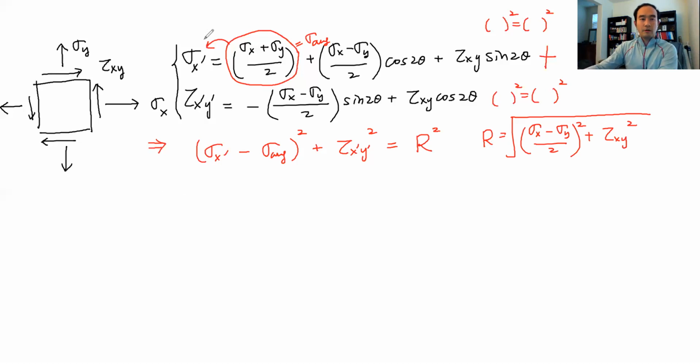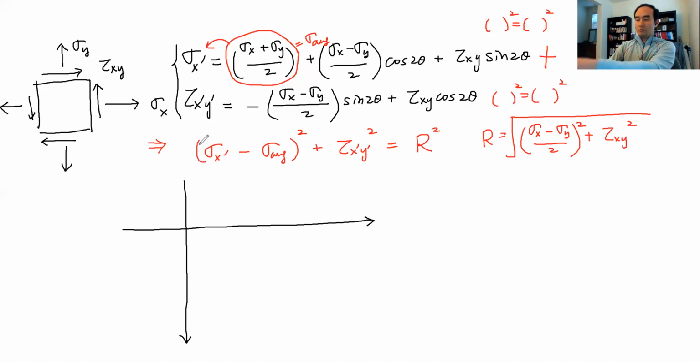Okay, so here I'm going to draw a circle, and that circle is called the Mohr circle. One of the things I mentioned is that when you develop the Mohr circle, there are two different ways, but according to Hibbeler's textbook, and I'd like to be consistent with its formulations and sign convention, he determined that the x-axis is the axis for the normal stress, sigma, and the vertical axis is for tau, the shear stress.